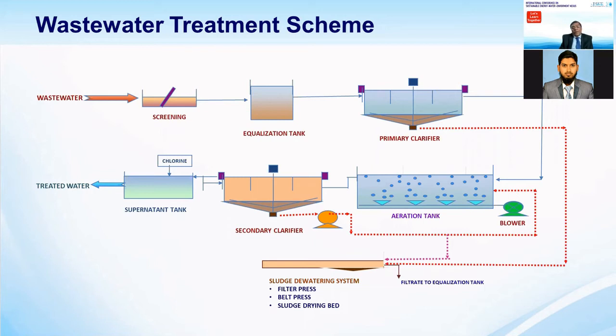For the sake of argument, if you have a vertical textile unit, you will sometimes have bleaching, finishing, dyeing, scouring, the various processes you will be implementing, and finally the washing. Every process has different contaminants. When you give the final wash, it will be a low contaminant. It means when your wastewater is entering the equalization tank, it will have flow variation and contamination variation.